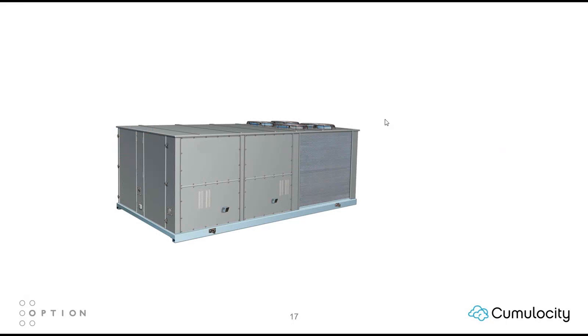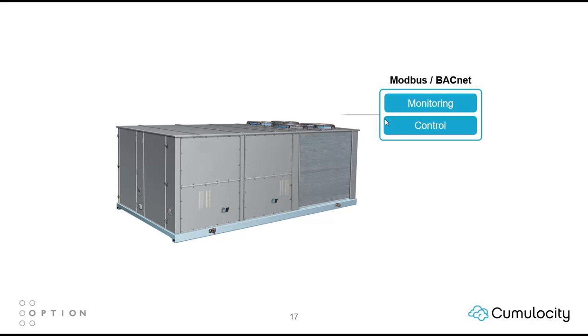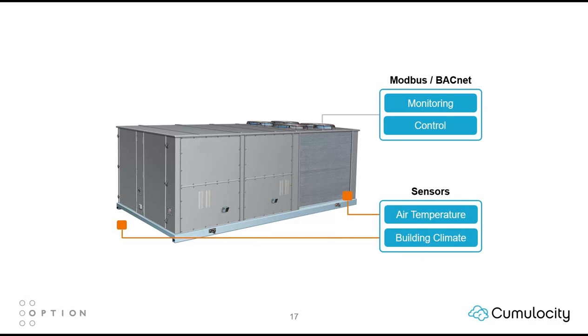Now, an IoT solution is built through connecting devices such as this HVAC, managing their data, and extending the service. To fully manage the environment, the connection has to be to both the asset via industry protocols like Modbus or BACnet, and also to climate sensors around the device and in the building to provide a data stream with a user view.